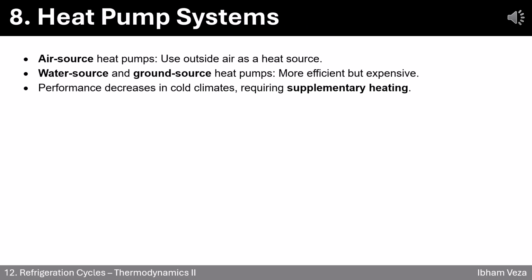8. Match the heat pump to the situation. Not all heat pumps are created equal. Choosing the right type depends on your environment and budget. Air source heat pumps are the most common because they simply grab heat from the outside air. They're easy to install, but struggle in very cold weather.